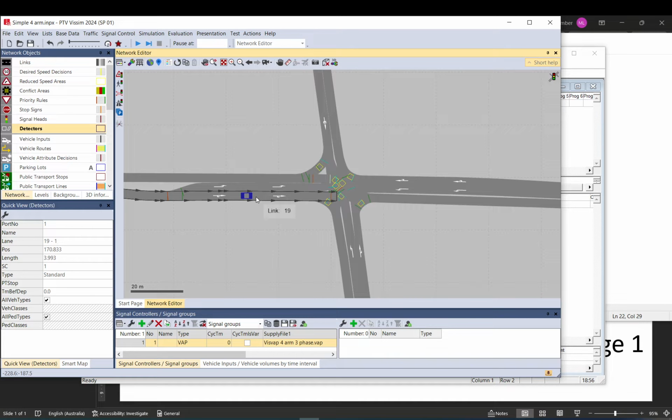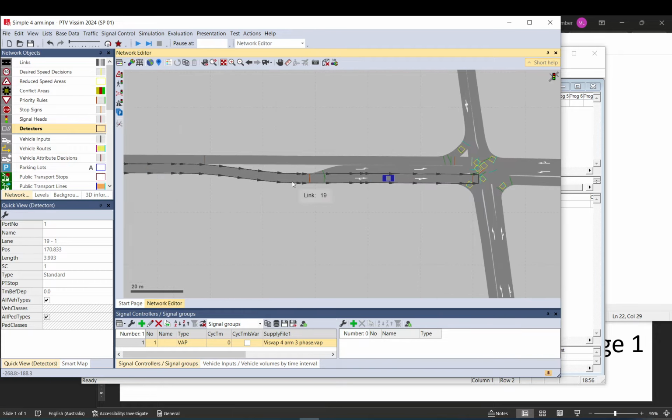If vehicles follow each other closely, that means there is a high demand. If the following times behind vehicles are great, that means there are big gaps between vehicles. That means the demand is low, so we can start thinking about checking the others. But if vehicles follow each other closely here, that means there is probably a huge demand, so we need to keep it open.